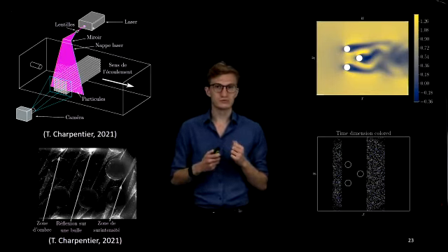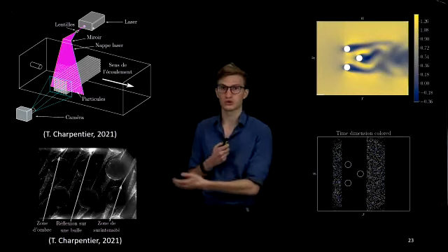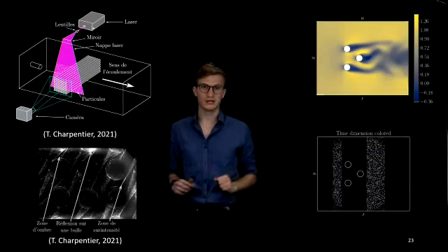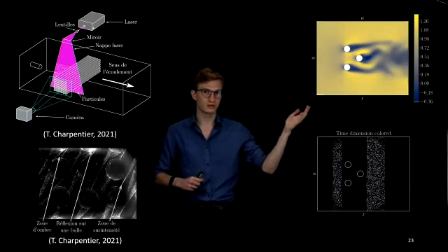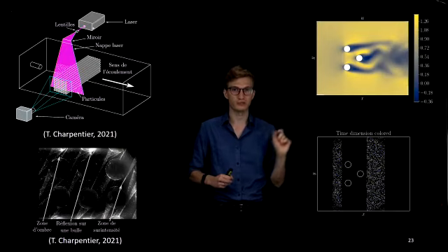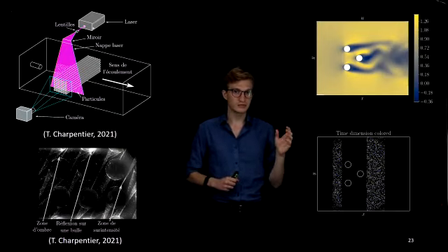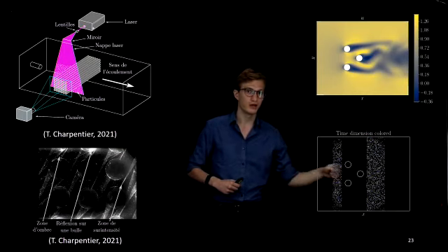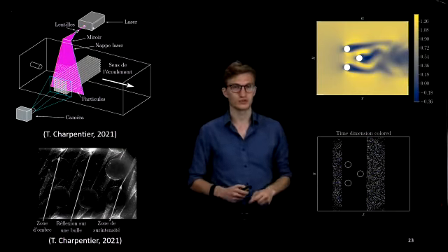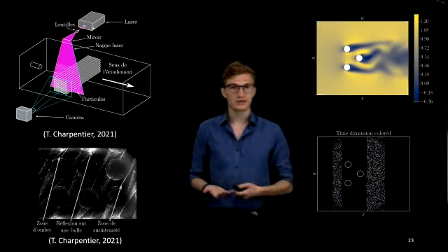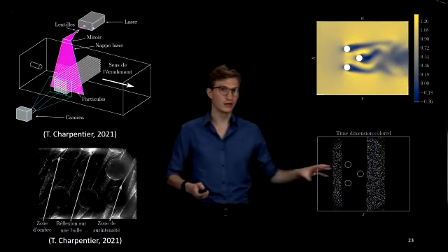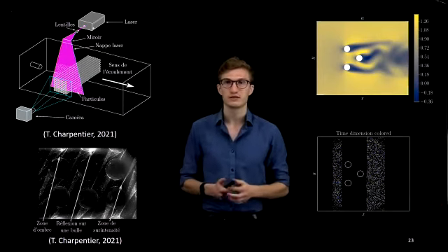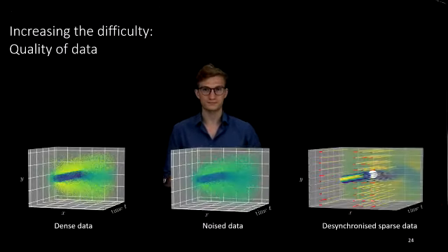So we wanted to know if it's possible to do that reconstruction using only information before and after the array of cylinders. To do that, we performed a reconstruction using this pattern, which is a bit simplified, with only 3 cylinders. We provided to the training measurements of velocity before and after, and also measurements of pressure around the cylinder that could be obtained with pressure taps, for instance. In some cases, we are able to reconstruct the flow in between the cylinders with good accuracy and also predict the force as well, which is quite promising for such applications.